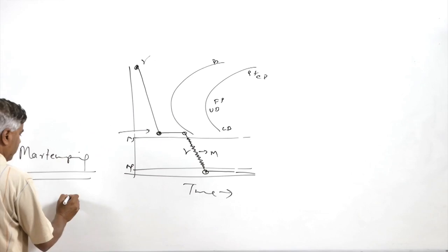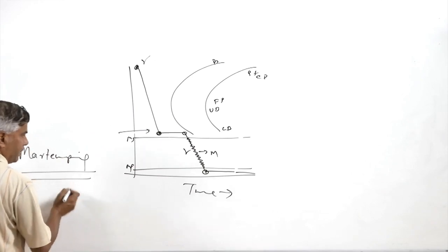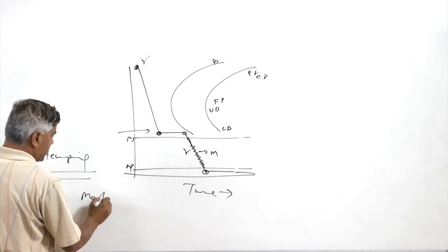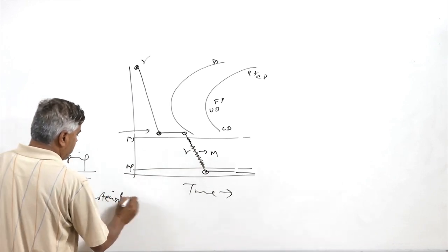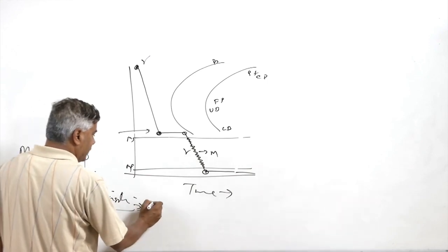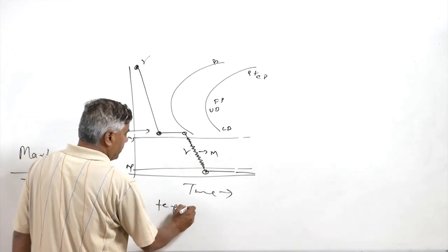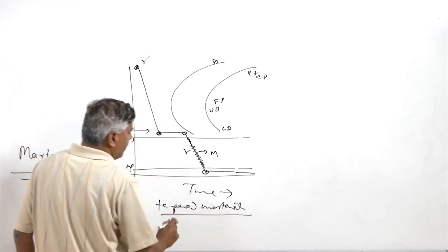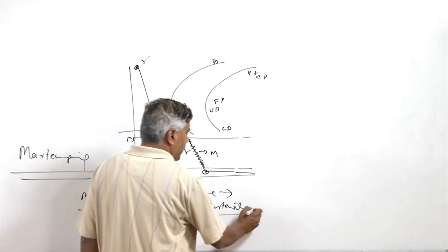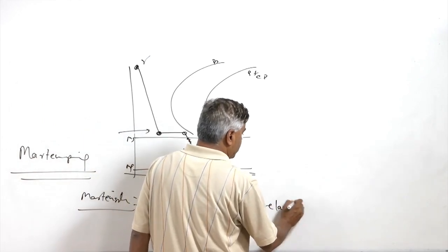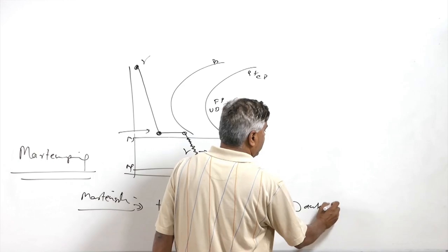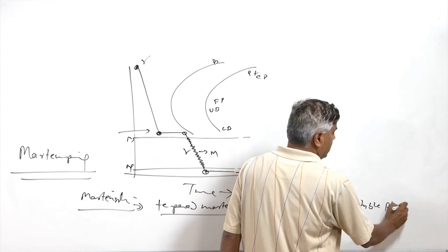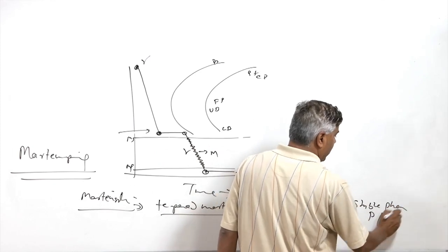During the tempering, two things will be happening basically: the supersaturated martensite which has been formed will lead to the formation of tempered martensite by rejecting some of the excess carbon from it, and whatever is the retained austenite will be converting into more stable phases like pearlite and bainite.